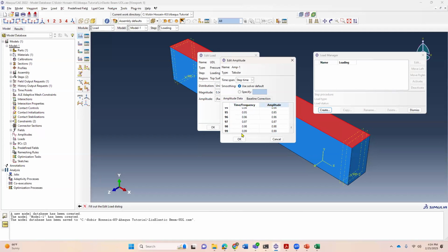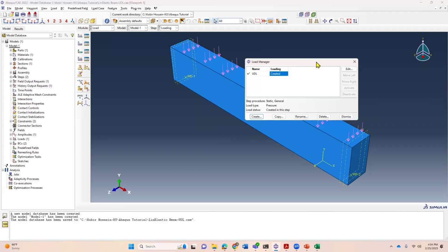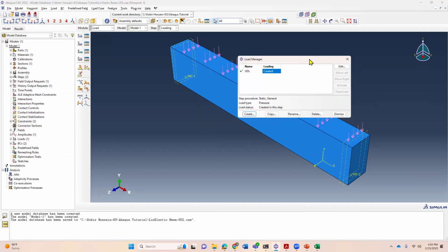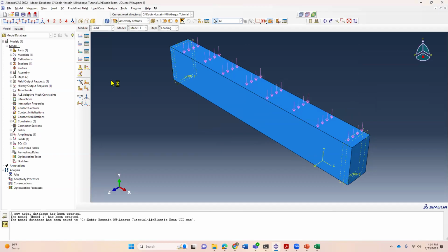So it's better to apply in this fashion. So we are applying this load sequentially and with uniform increment, okay? And also remember, in Abaqus the solver will make a small time increment to solve the problem and complete the analysis. So we have applied the uniformly distributed load here too.